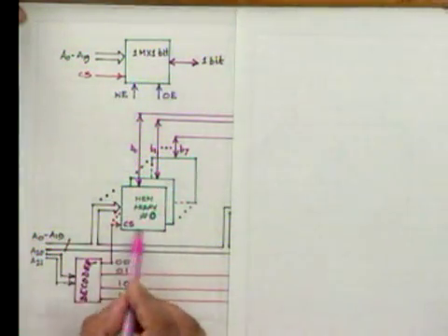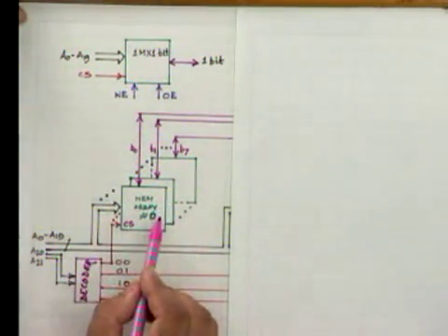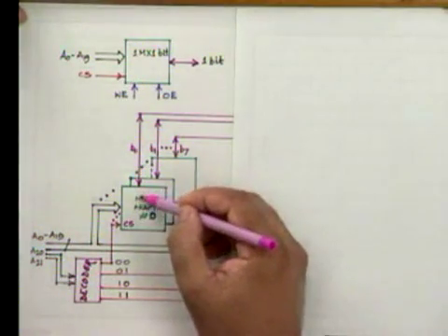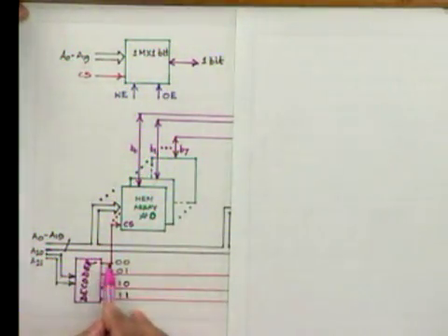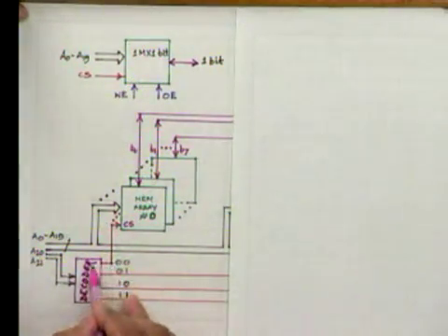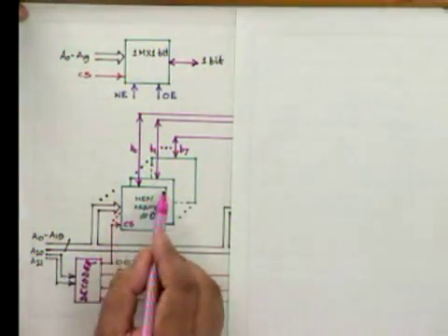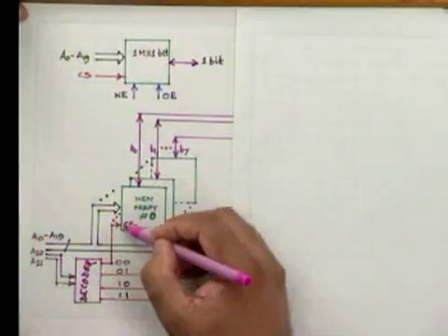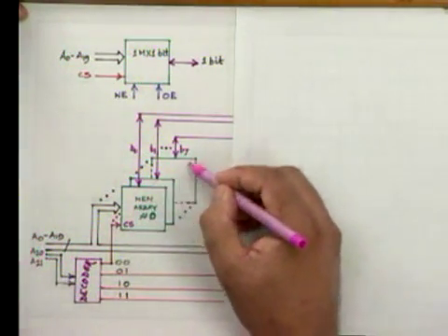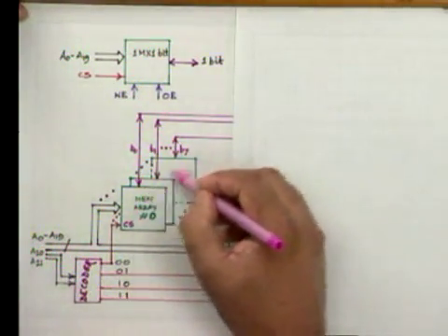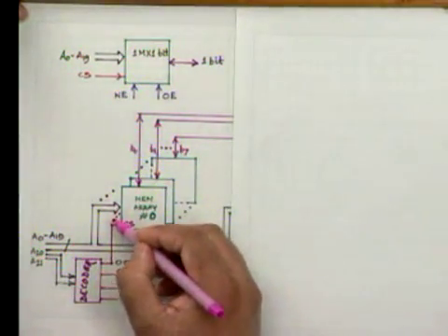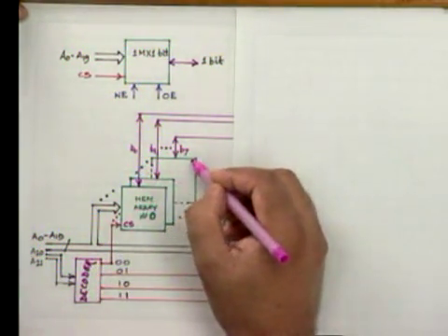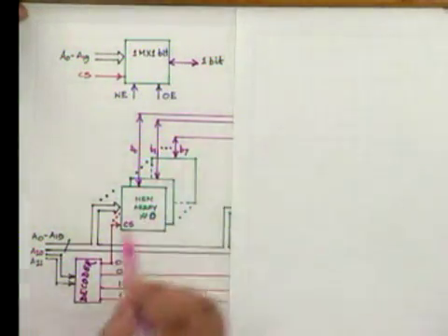For example, chip 0 in this stack is selected by means of chip select. That means if it is 0, 0, then this chip is selected. And when this is selected, all the chips in this stack are selected, right? This chip select line goes to all the chips in this stack.